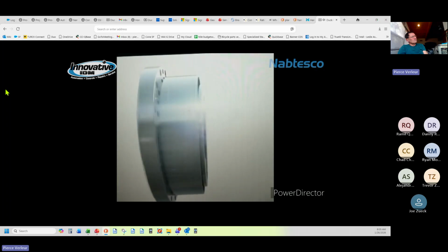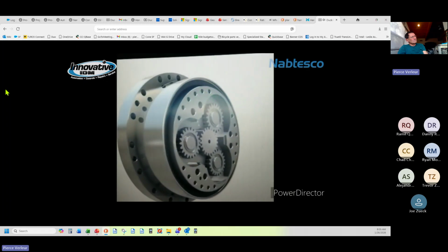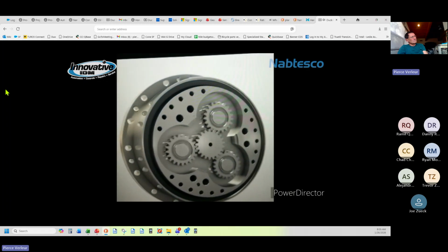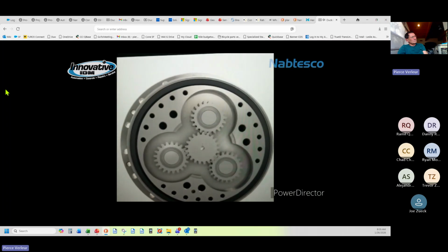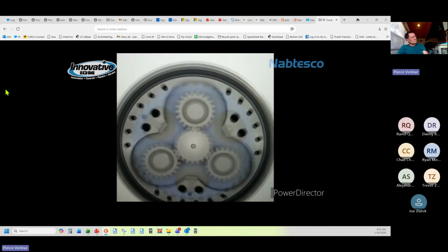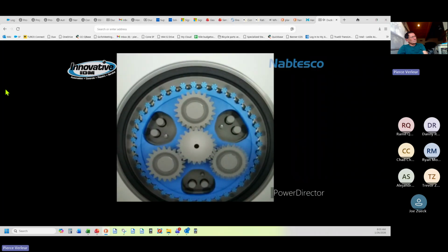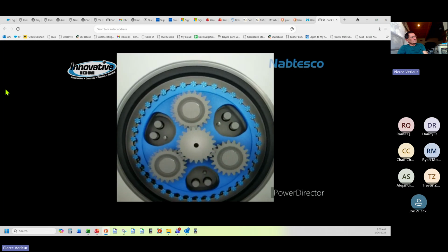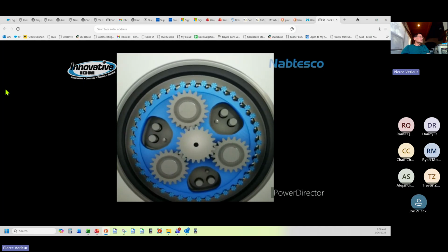So that's also, the pin and gear structure is going to enable you to have enhanced machine accuracy and durability. So the two-sided structure here gives you a high torsional rigidity, minimal vibration, high torque, and a minimum installation space requirement. So these guys are pretty easy to maintain. All you have to do is just grease or oil the gears from time to time.